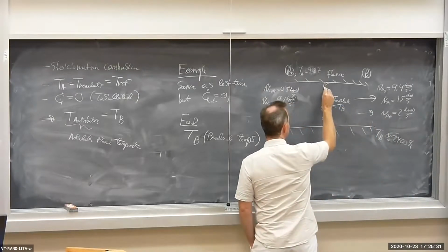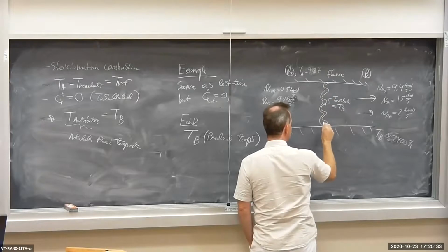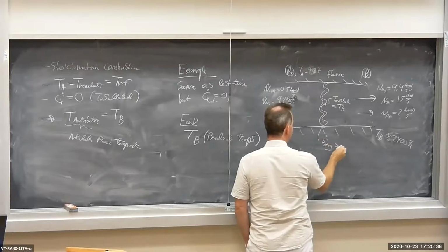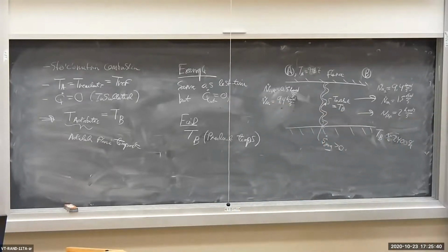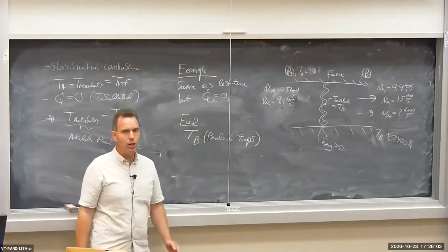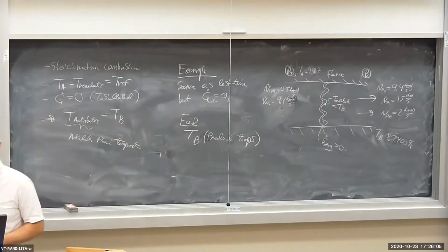The flame has a certain thickness, and right in here we have a bunch of entropy being generated due to the irreversibility of the combustion or chemical reaction. So if you do an entropy balance on this combustor, you better get an S dot gen greater than 0, else the reaction cannot occur. If you have a reaction and you find out that S dot gen is negative, then in nature, the reaction doesn't go the way you think it goes. It goes the opposite way.